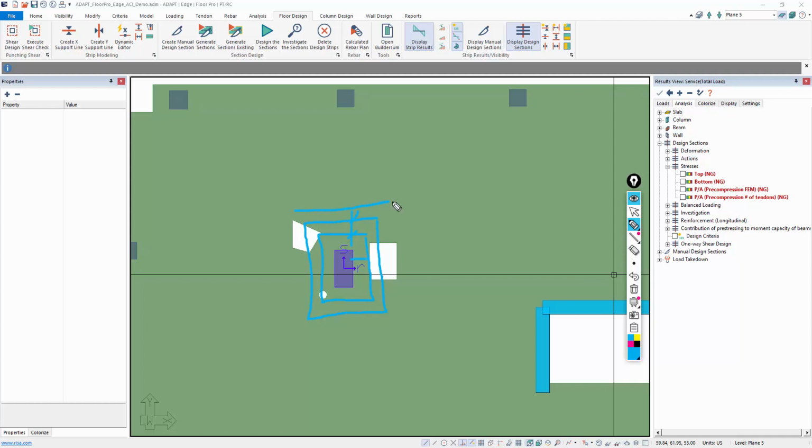But what happens is the program will check these layers, and if it finds that there's reinforcement required for each layer, the program adds that reinforcement between, for example, the column face, and we'll call these layer 1, 2, and layer 3. And so the number of studs needed between the face of column and layer 1 might be, let's just say, three studs. And between layer 1 and 2, we need maybe two studs. And between 2 and 3, maybe we need 1 stud.